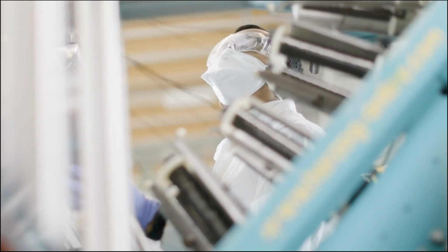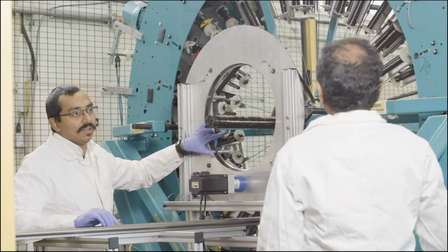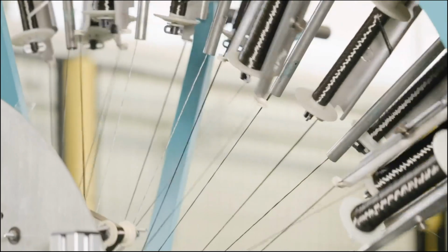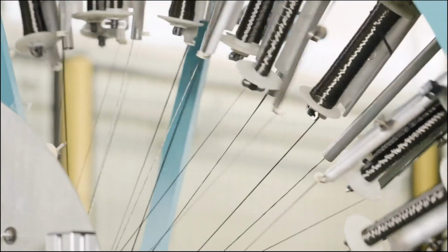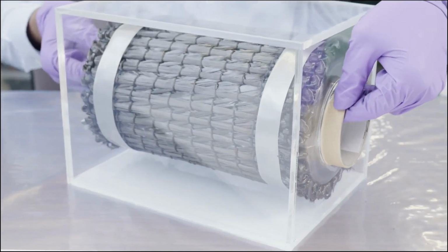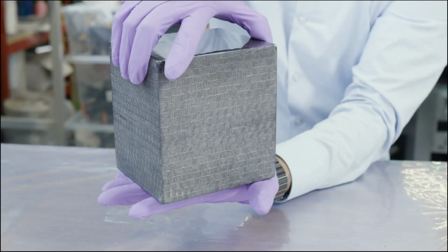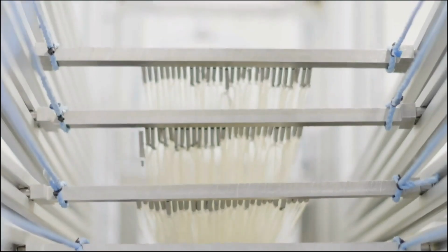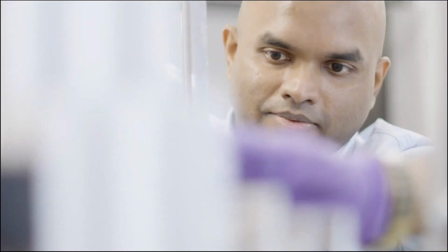3D fiber preforming using the patented multi-weft robotic system that we developed in this project is almost like additive manufacturing or 3D printing. Now we can place fibers in any orientation, any thickness along with through thickness binders, mixing various types of fibers such as carbon, glass and ceramics.